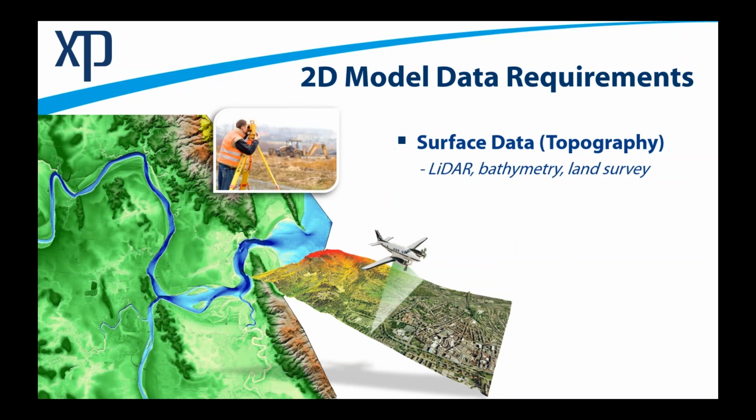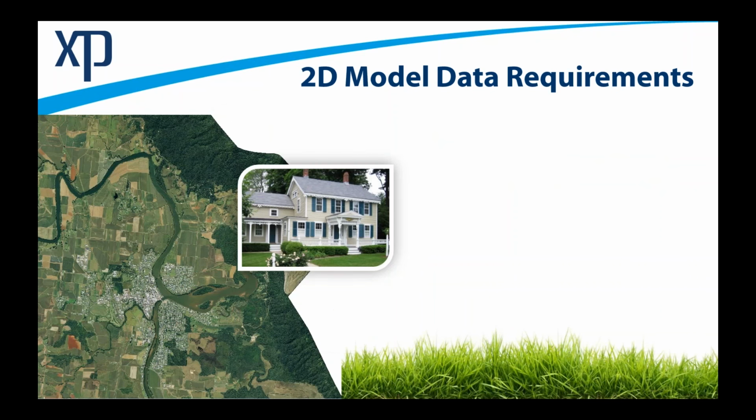The next piece of information that's required is your land use information. This is typically used to determine how vegetation changes throughout the catchment, because that in turn affects the flow characteristics and how free-flowing the water is, or how retarded it is, I guess. So long grass versus short grass or concrete is going to have different... Or even buildings. Yeah, buildings. And the other extreme.